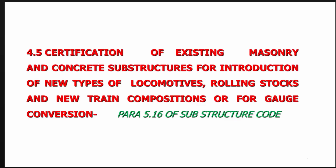This is the chapter about the substructure code, very important because we know the axle loads are normally not increasing much, only 8%, from 23 to 25 ton, whereas our longitudinal force is increasing from 50 ton to 126 ton. For that, the substructure code has to be checked.